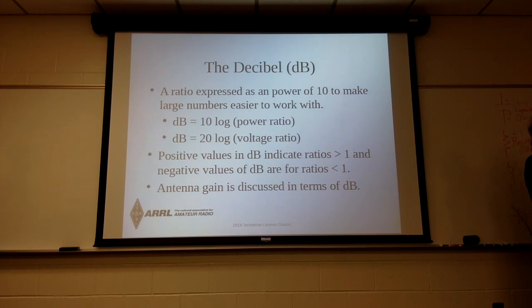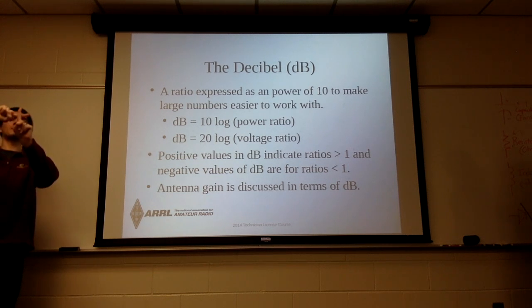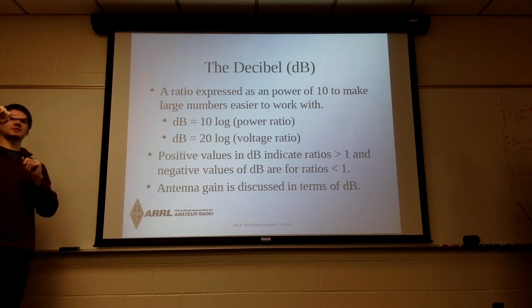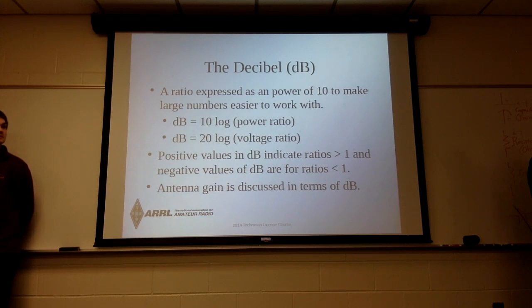If you have this Yagi, would it matter what polarization? What you're talking about is actually secretly two Yagis. One array is pointed in this direction. The other is pointed in this direction. You're driving two antennas at the same time, and that will eliminate the need for polarization. That's what we use to talk to satellites, because the satellite could be tumbling and it's polarized all over the place. But when you have two Yagis that are vertical and horizontal, it doesn't matter. It'll be effective no matter which way.